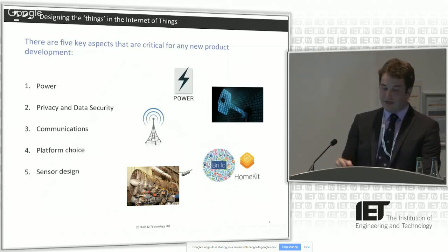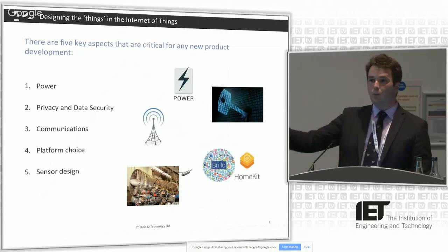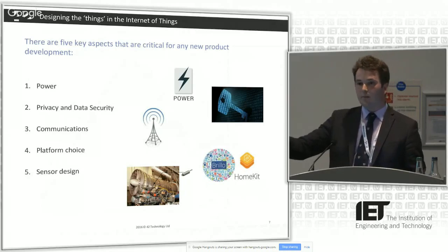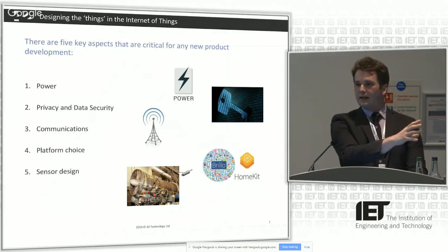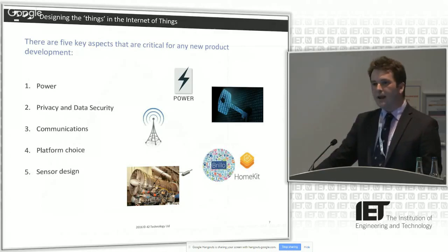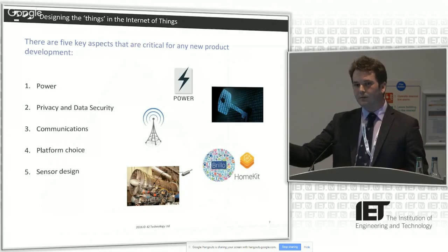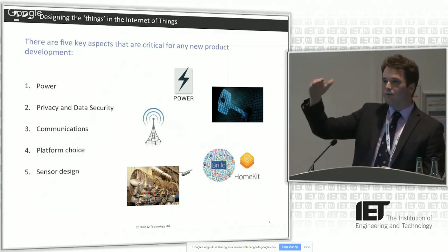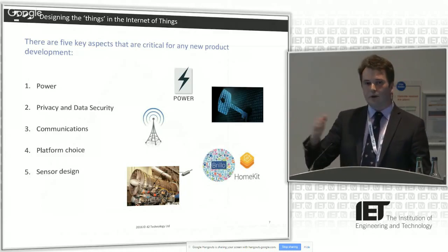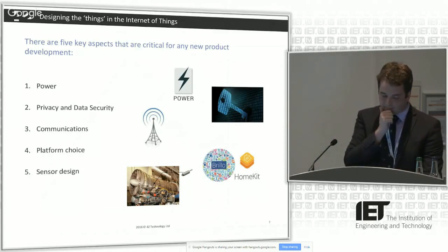And furthermore, as devices get cheaper, the number of devices you're going to have, for example, in a house, trying to talk to the Wi-Fi router or trying to talk to your dedicated home hub is only going to increase. When you've got your barbecue meat temperature sensor and your fridge that knows what's in it and the floor that knows how much you weigh, all shouting at the home hub, trying to get this information back to the cloud, there's an awful lot of things for it to listen to. And again, if you want to increase the priority of your device, you might have it shout more frequently. But if you're looking for low power, again, battery life comes into play. So you've got to be a bit careful with that.